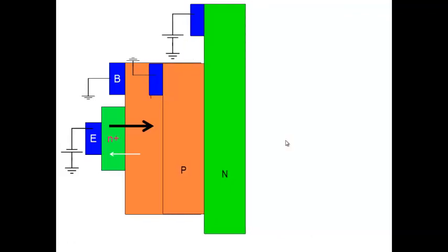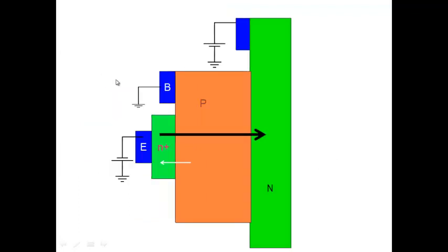Fuse it together, and now we realize when you fuse it together that the original P could serve as P for this particular diode also. And for this contact, I need not make a contact here. The original contact can serve as a contact for this one also. So we are fusing these two diodes and realizing that the same P can serve as P for this particular one, and the same contact can serve as a contact for that one. So when you fuse them together, this is what you end up getting. Take two PN junctions. It's not simply two PN junctions externally connected by a wire. Two PN junctions actually fused into each other. Okay, and this is what you get here.